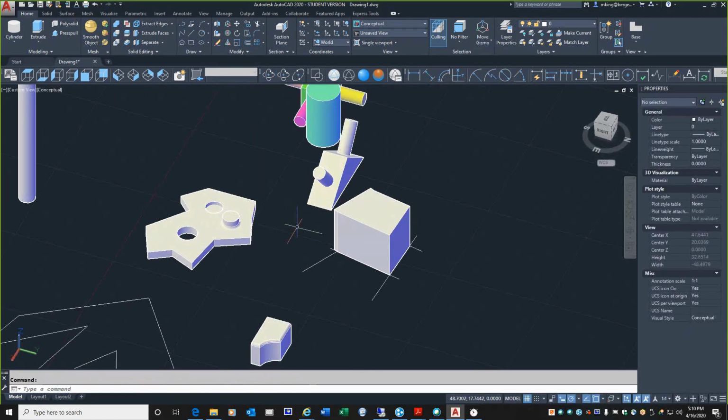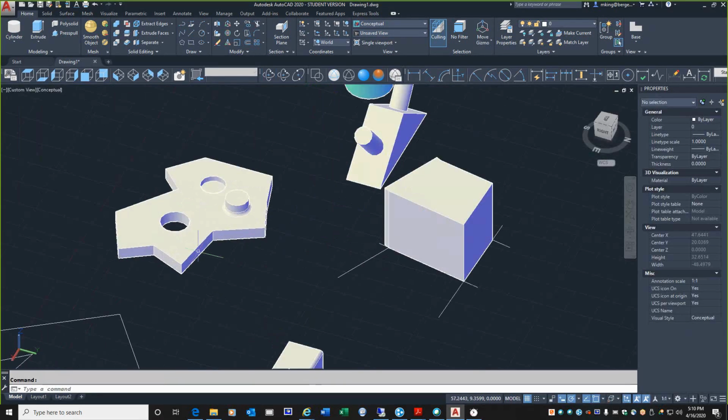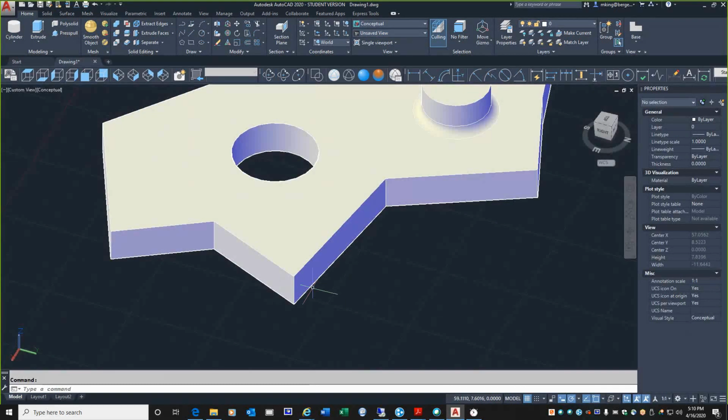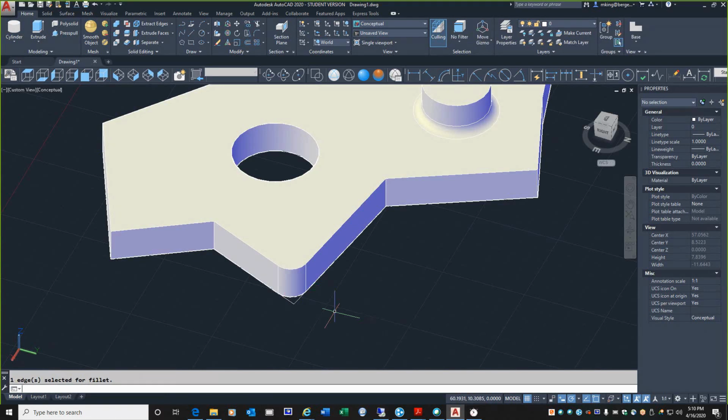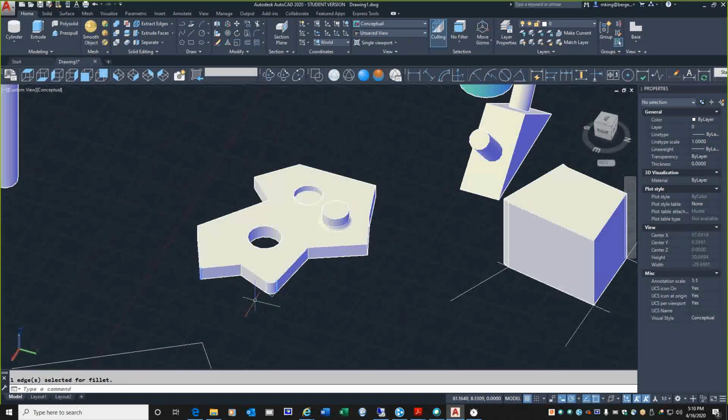So now you have ways of rounding surfaces off. If I needed to round off this point, it's pretty sharp, right? I go to fillet. I would select this edge here, and let's say we'll go to 1/2 inch. I'll say 0.5, enter, and it's only that edge, so second enter, and that rounds that right off. Remember, this line's left over from our original geometry.